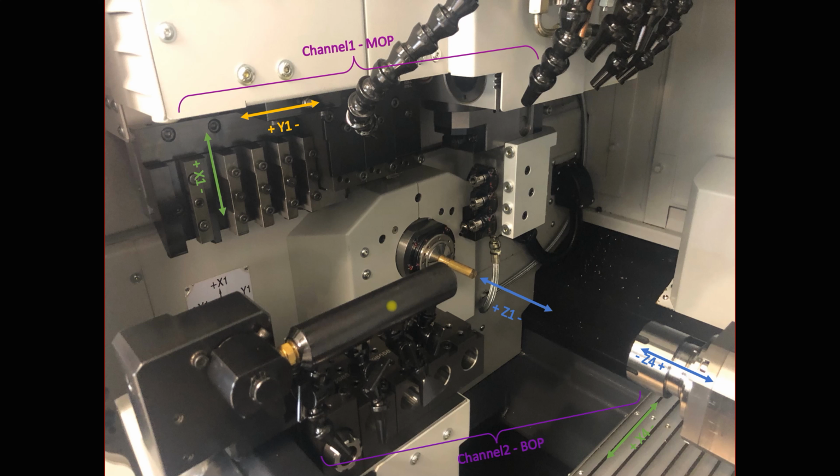The resolution in axis of our machine is 0.1 micrometer. It means that when entering positions in a program, we can give 4 digits after decimal point when we would like to enter a value in millimeter. The same it concerns displaying of positions on a machine.